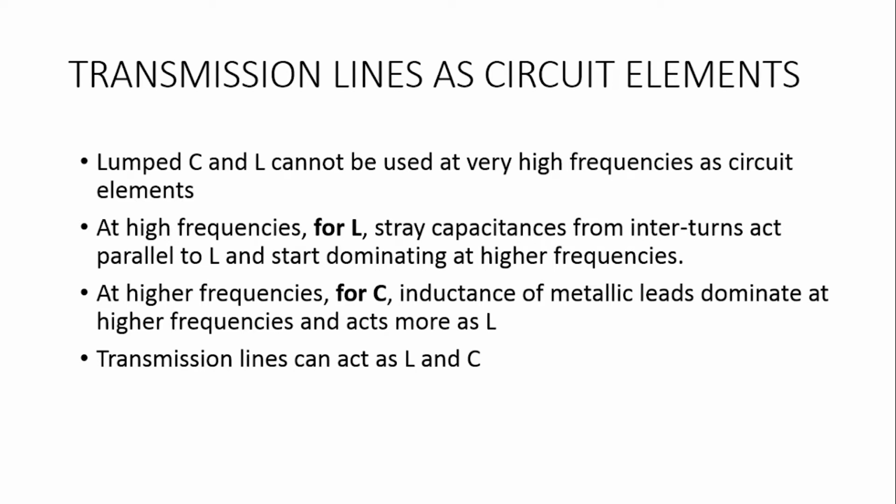That is because at higher frequencies, when we consider inductors, there are some stray capacitances that are developed due to the interturns, and at very high frequency these stray capacitances will behave in parallel to the real inductance value, and they will start dominating at very high frequencies, so that can affect the proper inductance of the component that we are using.